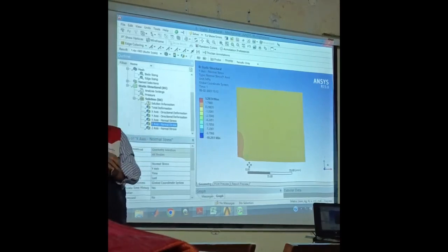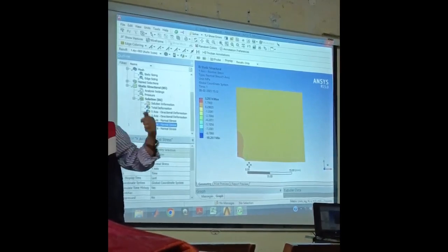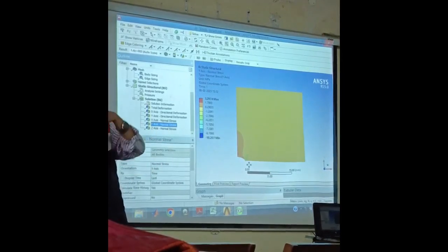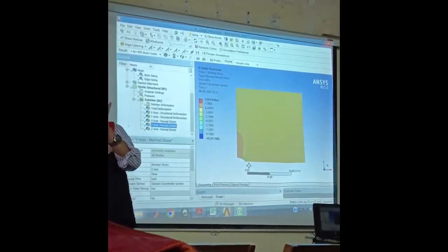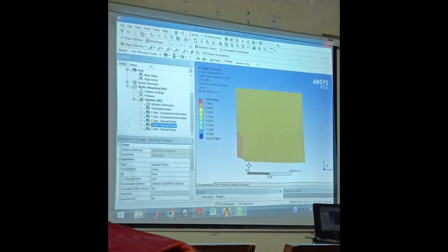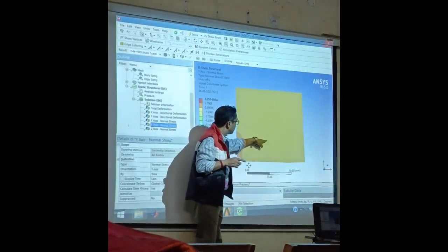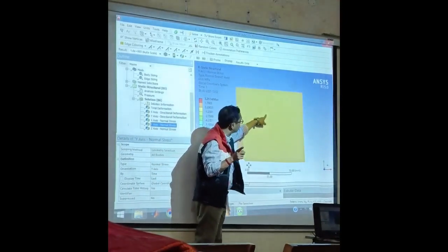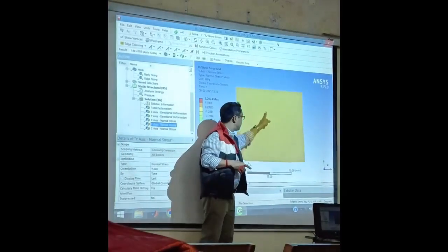Then due to the cumulative effect, this one will create 3 sigma in this zone, and here it is minus sigma, due to axial load. 3 sigma and minus sigma. And when I have load in these directions, 3 sigma, here it is minus sigma. Due to the combination of these 3 sigma and minus sigma, one case sigma is double of the other. It is expected that your windows and doors are supposed to be this shape. Otherwise, if it is reversed, you have seen this, no?